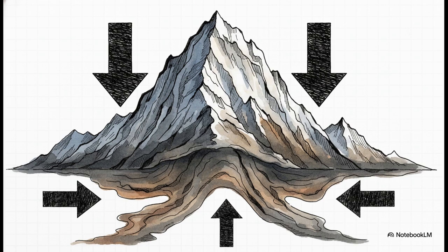The elastic limit for typical rock is about 30 times 10 to the 7th newtons per square meter. Plug that into the density and gravity equation, and you find the maximum height before the rock fails is roughly 10 kilometers. Mount Everest is right near this limit, because if it were any taller, the extreme shear stress would cause the solid rock at the base to permanently deform and just flow outward like plastic mud.